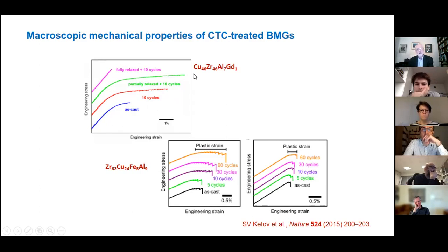So if you think of embrittlement of the glass by annealing as seriously bad news, this cycling afterwards allows you to bring it back from the dead. So probably this idea of the Romans throwing themselves into cold baths and hot baths was not such a bad idea for rejuvenation. If you fully relax the glass, it seems to be irrecoverable. Presumably it becomes so homogeneous that when you then cycle it, you don't have different regions acting against each other to give a rejuvenation effect.